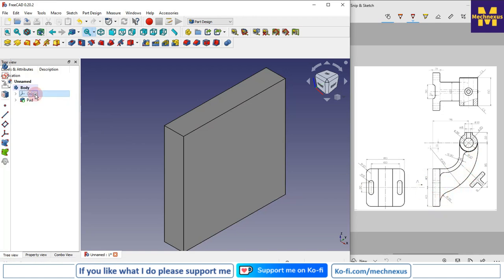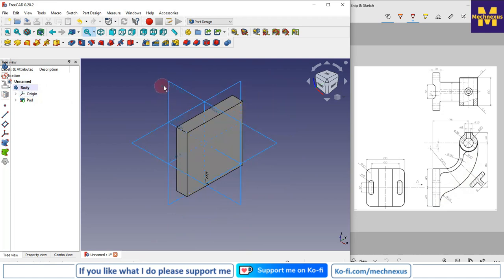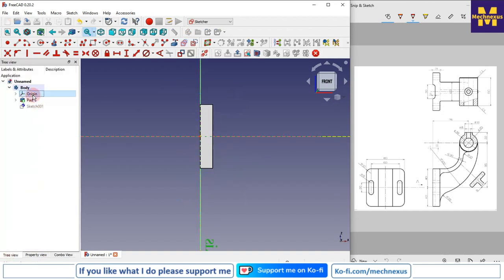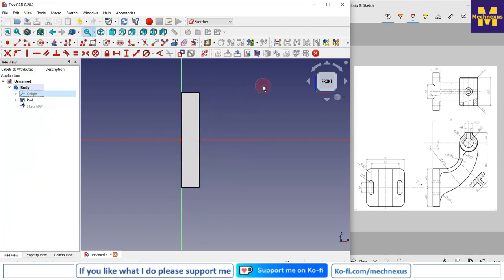For this I will again turn on my origin plane, select this XY plane, and create the sketch, and I will turn off my origin plane. Here is a radius of 25.